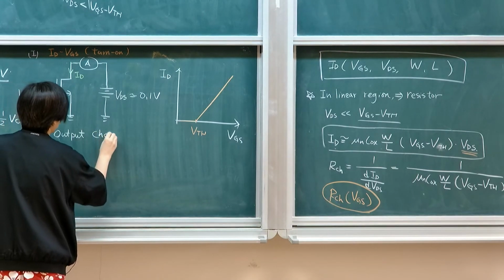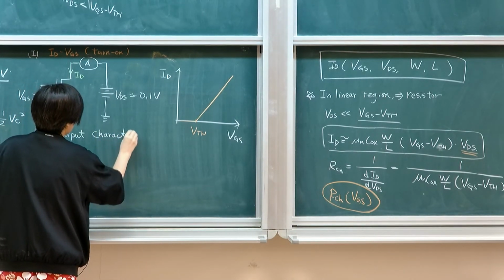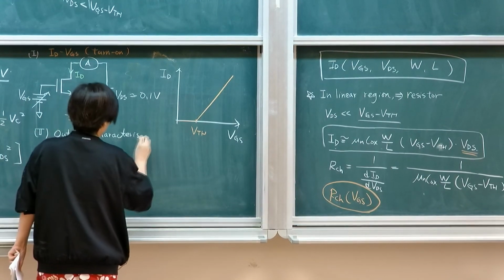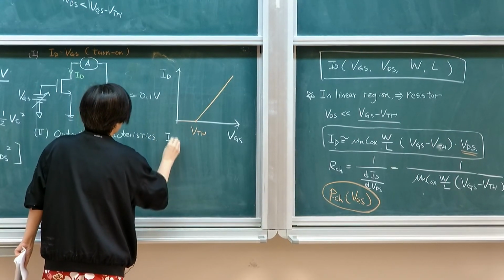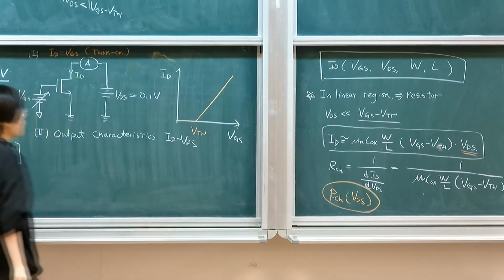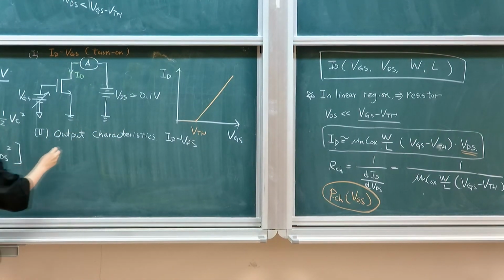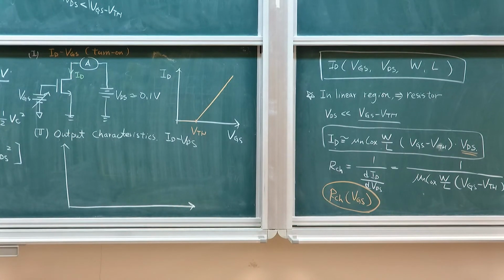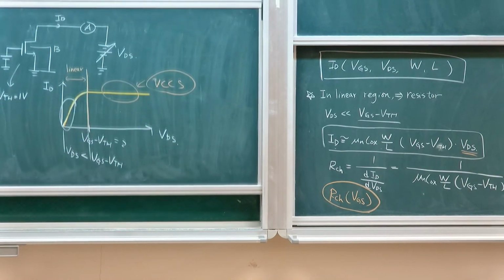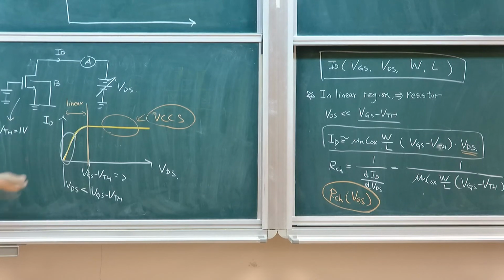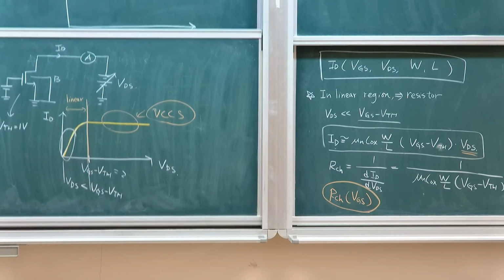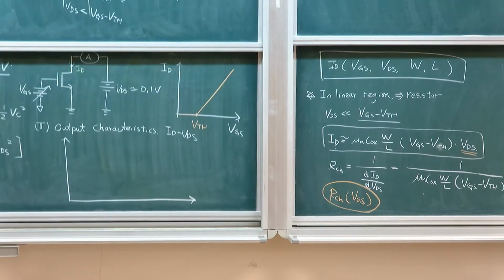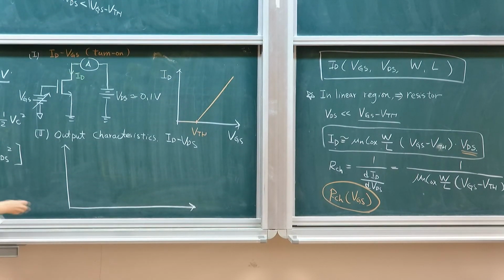Output characteristics are typically referred to as VI, which in this case is ID versus VDS. So that's the current equation. Typically the measurement setup is like that, but we will give you different values of VGS, so it will be multiple curves. If I try to draw multiple curves using the parameters given above, I ask you to draw the characteristic of ID versus VDS.